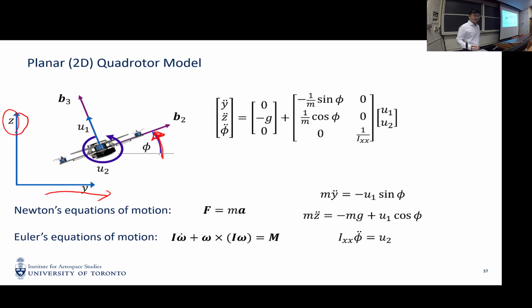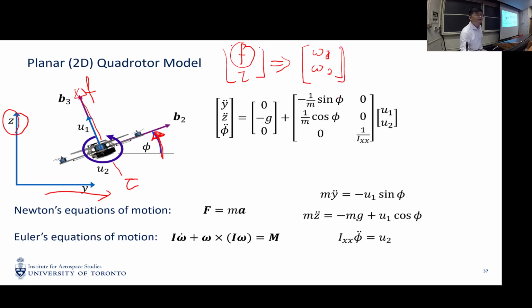So as we can see, because of the thrust mixing algorithm we are able to control the total lift F and the total torque tau on the quadrotor. So if we get the total F and total tau, then we have a way to transform into the spinning velocity of each rotor, right? So this is covered in previous slides. Okay. So in the later slides, I will just use F and tau as our direct control input.